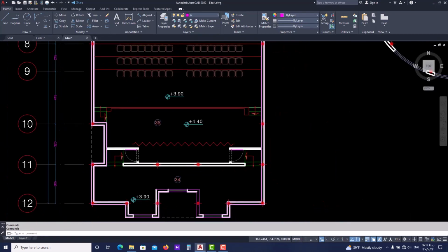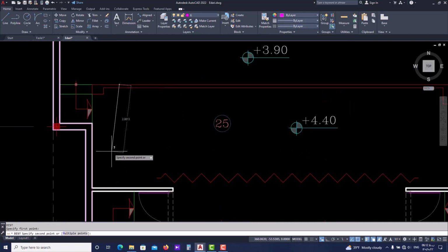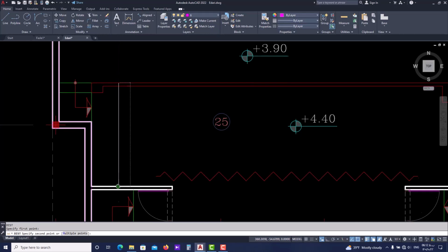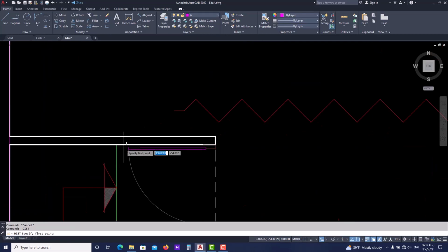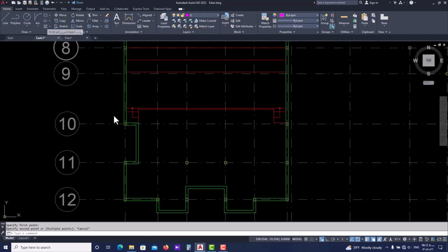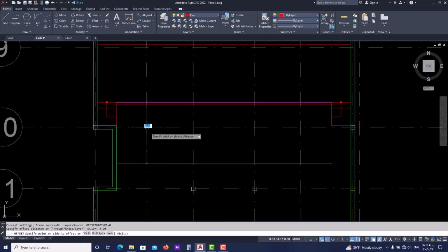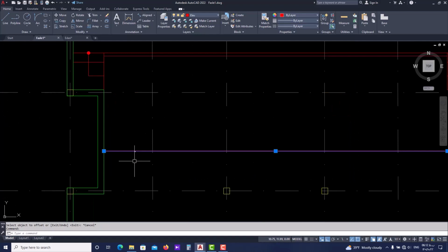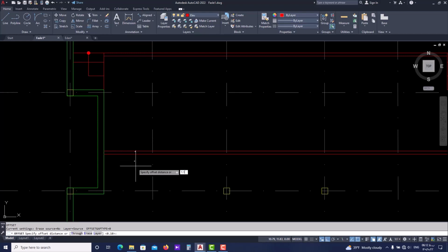It's kind of ironic, I know. Alright, first let's check the distance for this wall, 3.20, okay, and a 10 cm wall here. And after that, we have a 1.10 meters distance again. What was this again? 3.20. All right. Okay, so in here, we need to offset 3.20. Then again, 10 cm. And after that, 1.10 meters. And another 10 cm down here.